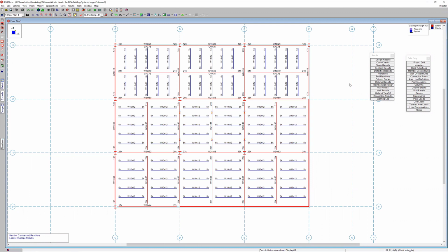Now you can make these hanger columns be, quote unquote, a lateral member, which means that they would show up in RISA 3D. They don't have to only be gravity members. If you want that element to show up in RISA 3D, you can define them as lateral members. That's fine too. But again, generally speaking, from these hung mezzanines, we're not going to have lateral diaphragm analysis being done on these hung levels.